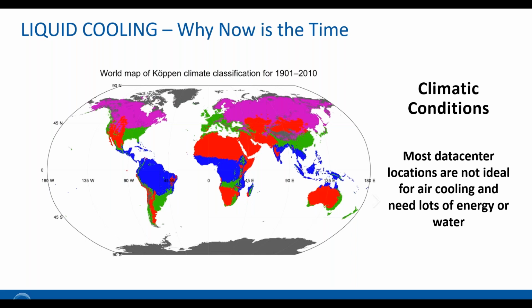Going forward, as the data center industry expands and builds up capacity in more and more locations, driven by cloud buildups, and also as enterprises want to consolidate increasingly in co-location facilities, that means purpose-built data centers, again in more metros. This balance will shift to locations where climatic conditions are not really ideal to drive aggressive PUEs with air. So liquid cooling there is a response.